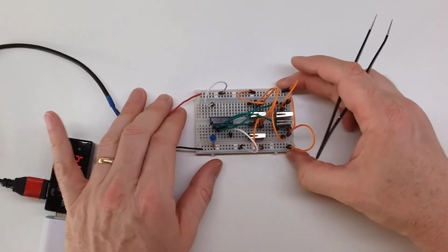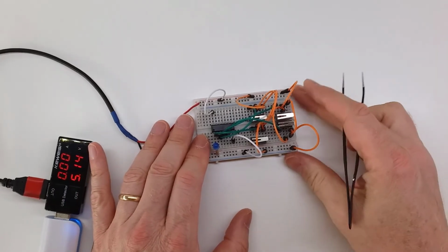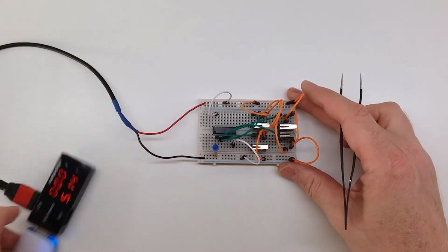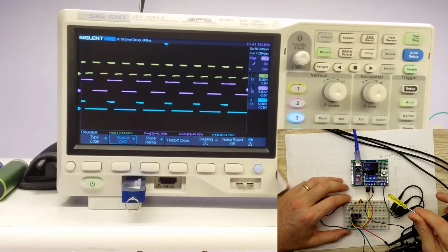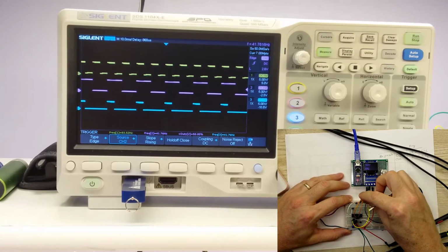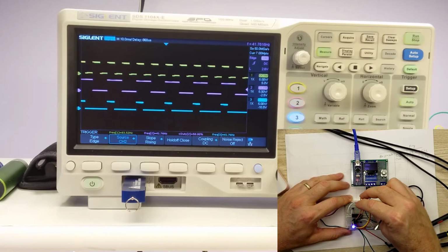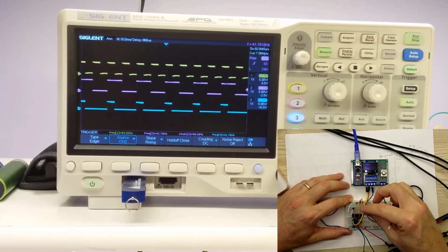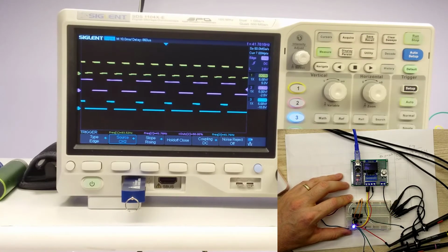So I think we'll take this over to the oscilloscope and take a quick look at that and see how fast it can keep up. I have not tested that on this chip, so I don't know what to expect. Now I've got that dual quad input, so this has 4 inputs, and right now I just have 2 of them, inputs 3 and 4, tied to high, so it's technically just a dual input, which is going to be the 2 signals, the yellow and the purple on the oscilloscope. And just like before, the yellow right now is at 83 hertz, and the purple is going to be exactly half of that.